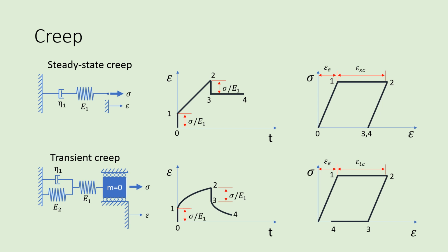So in these models, since we're looking at stress and strain, we have normalized force for cross-sectional area, and we are now applying a stress instead of a force to the object, and we are measuring displacement in terms of strain, or displacement normalized by initial length.